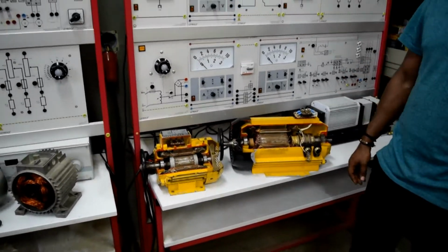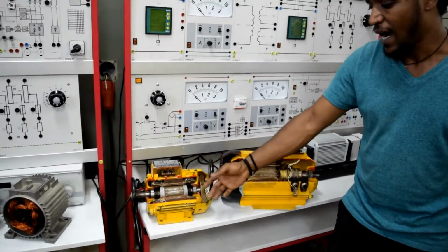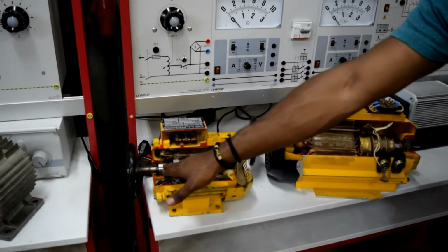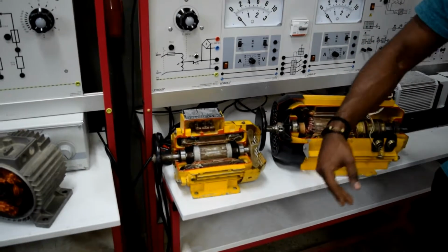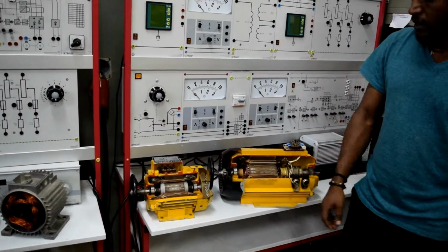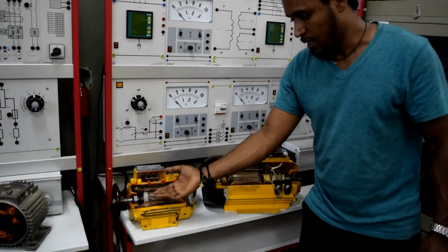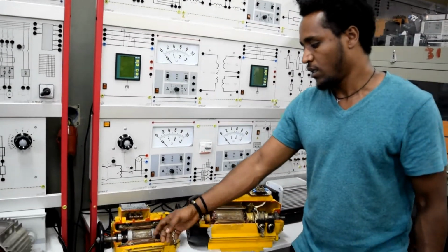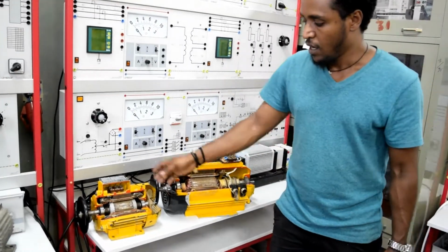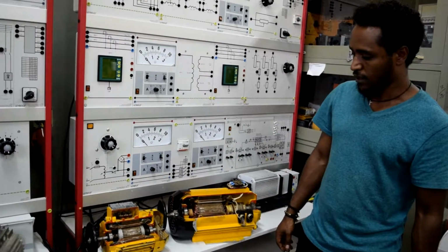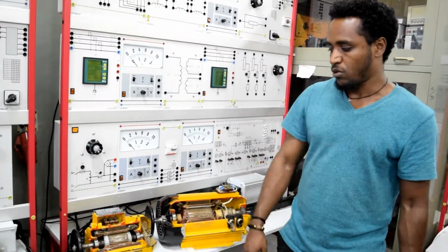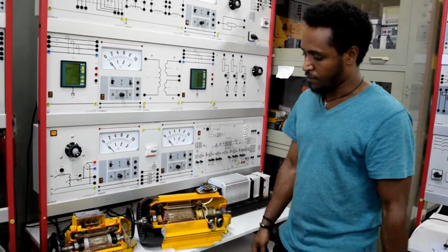But the other disadvantage for a squirrel-cage is we can't add additional resistance to the rotor because there are no slip rings and brushes here. If there is no slip ring, there is no way to add additional resistance. If there is no way to add additional resistance, that means it's not possible to reduce the starting current by using additional resistance connected to the rotor, even if there are other means to reduce the starting current. And also we can't increase the starting torque by using the rotor resistance. And also we can't vary the speed torque characteristics for a squirrel-cage one.